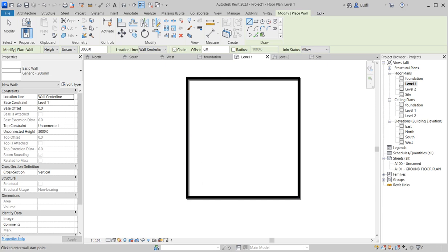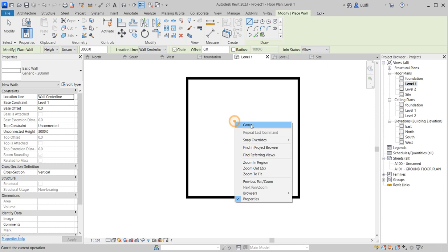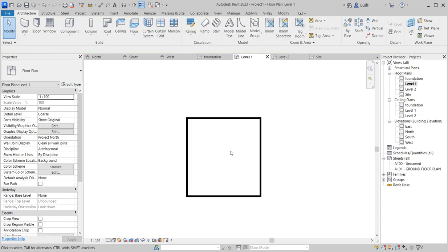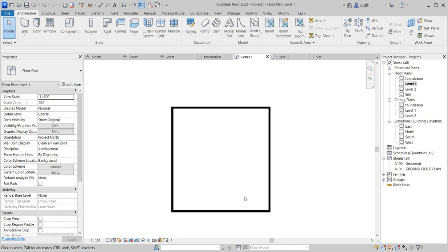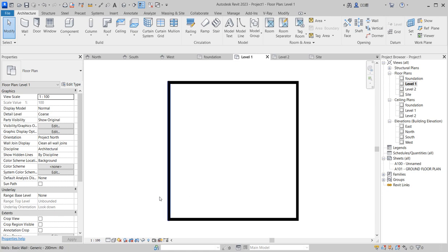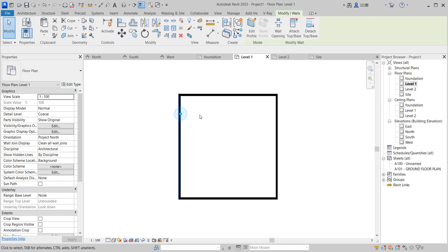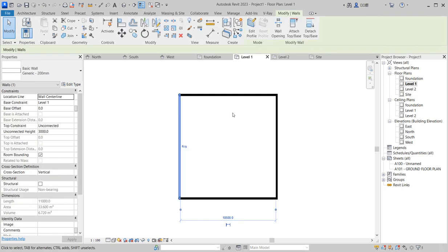So we are starting the project straight up, and let's continue with the process one after the other. This is the boundary, and this design has no surface plan, so the whole design will not take off from there. We're going to start creating the rooms one after the other. We only have one room on the ground floor, as big as the house, and the other facilities are to follow. You click on the wall, then you start demarcating one after the other.